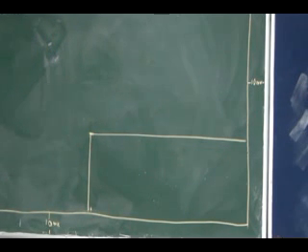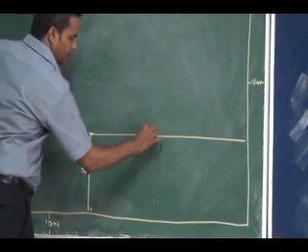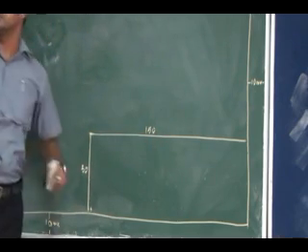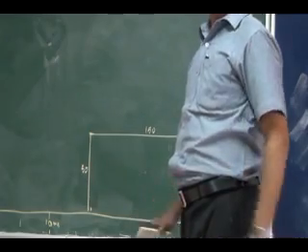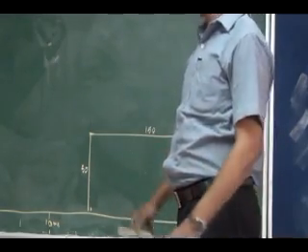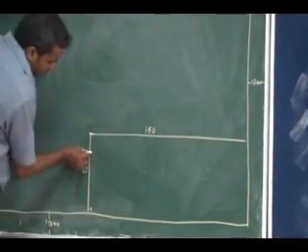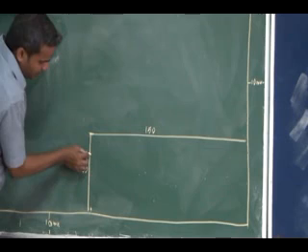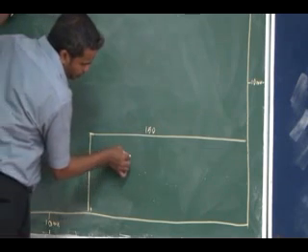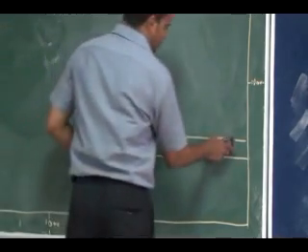This is the title block. The title block height is 50 and the length is 150, all in mm. The vertical line length is 50. Now I am going to split this title block to represent the details of the drawing. Since it is 50 mm in height, the first block I am going to split as 10 mm.